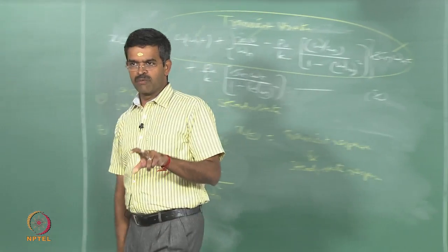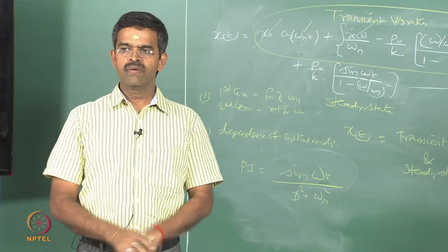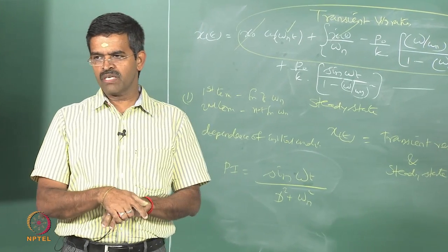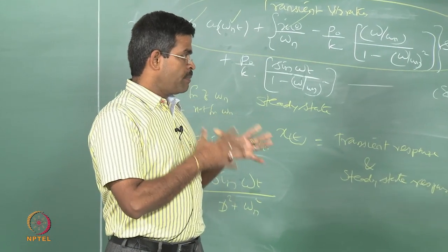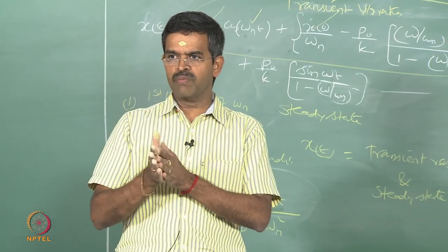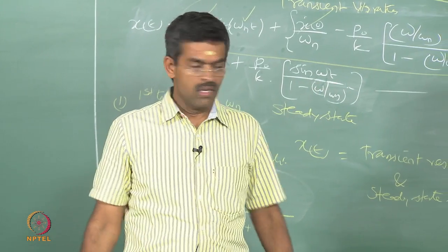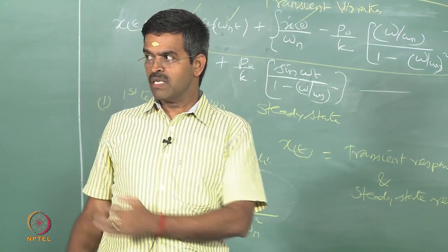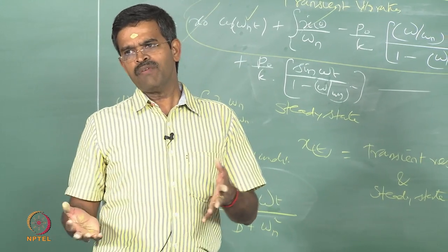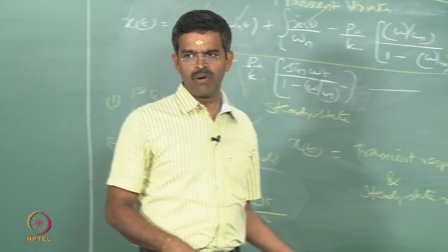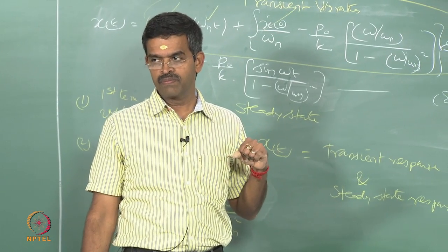So, in this lecture we have discussed two things. One, we have compared Coulomb damping with frictional or viscous damping, and we understood why Coulomb damping or friction based damping models are not effective for offshore structures, though there is dissipation of energy arising from friction between two particles or two members in any joint in an offshore structure, because the decay is linear and takes a long number of cycles to decay, whereas in instantaneous response steady centering capability is required in an offshore structure. Therefore, in reality we must adopt a damping model which is proportionate to the real behavior, which comes from viscous damping, number 1.